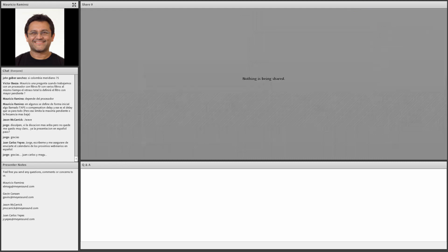Let me close this. And this filter is not only part of the Meyer Sound controller Galileo, that is digital, but in the days of analog controllers, Meyer Sound had 3 analog controllers. They are called LD1, LD2, and LD3. And the low-pass filters for these controllers are exactly the same filter as this. Only that in the analog controllers, you cannot have as many frequency ranges as you can have in the digital controller. Let me show you a high-pass filter in the digital Meyer Sound controller.